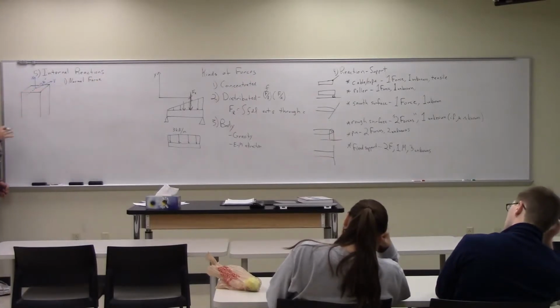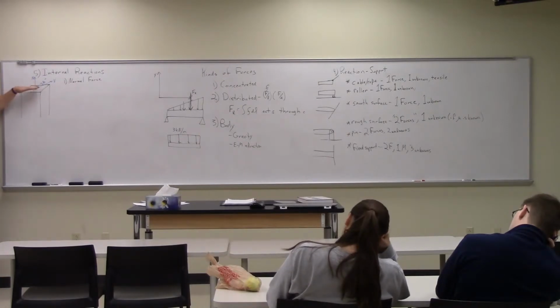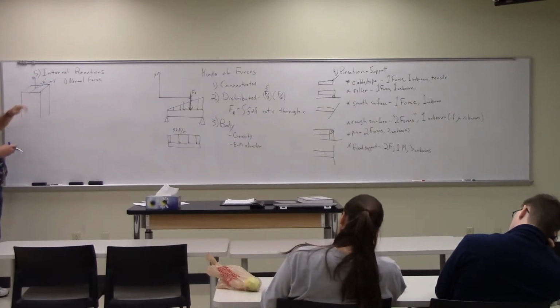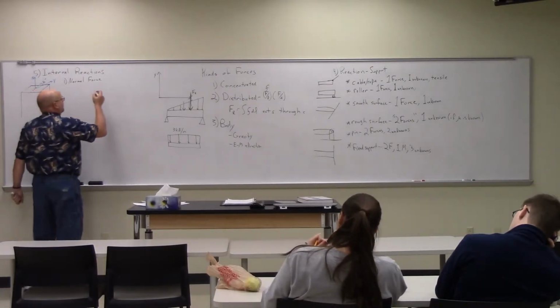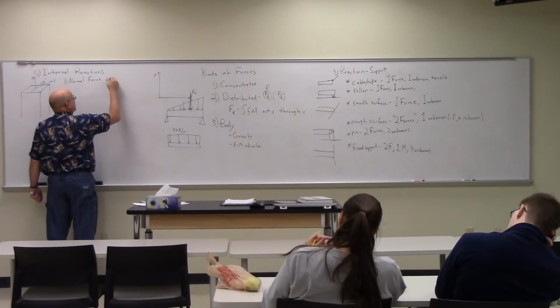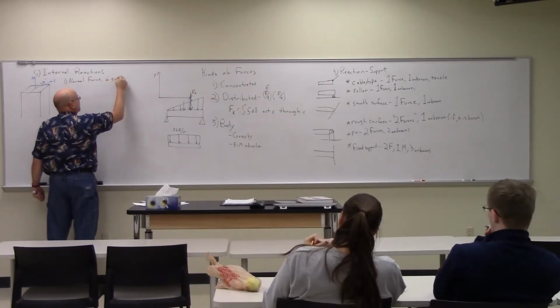Right, so if this is a beam that has some external forces applied to it, and I cut it off, if it's in equilibrium, then there has to be an internal force here to balance the externally applied forces. You guys remember that process? Right? So if there's an externally applied normal force, then there has to be an internal reaction normal force, perpendicular to the surface.